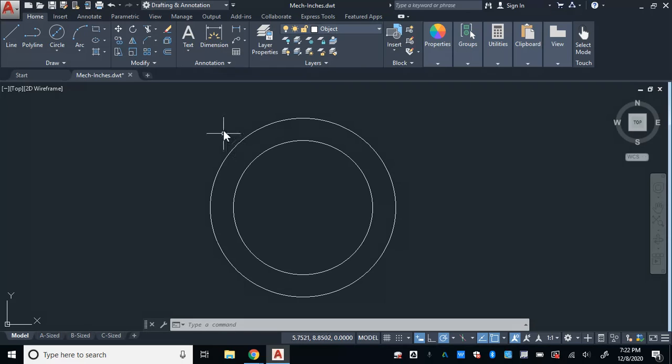The best way of doing it would be to take your time and draw it correctly for one of them, which in this case, I'm going to do the top vertical part here because it's exactly in the middle. It's dead center at the top, which is where quadrant comes into play. And then I'm going to use the polar array to make copies of it that go around the outside edge all the way around. So I'm going to take my time and build the top portion of my gasket here.